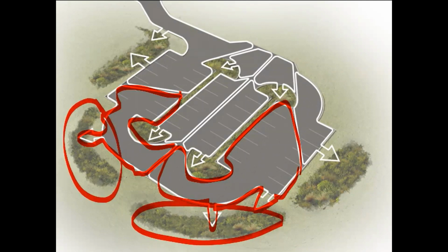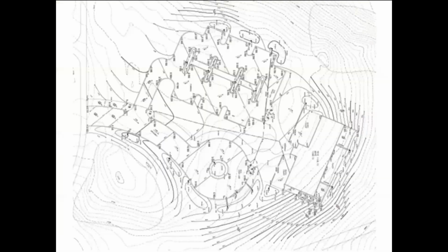What do you do for the actual curb cuts? What do you do for raised drop inlets if you have them? And what do you do for regular drop inlets if you need those as well? So this is an example of the sort of plan that you're going to have to create. And the basic idea is that you want to create these bioretention systems that are downhill from your paved areas.